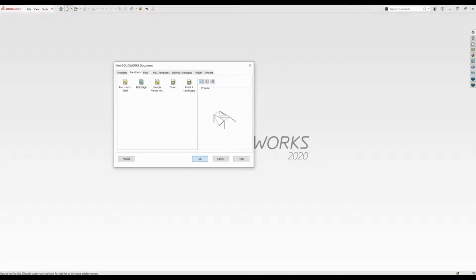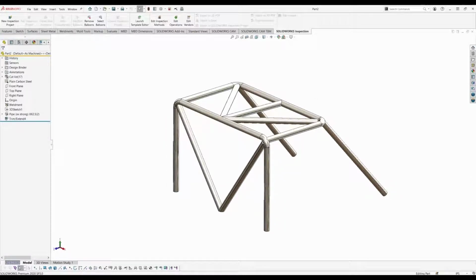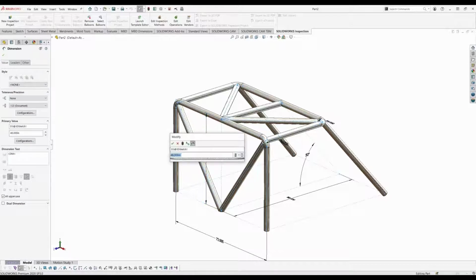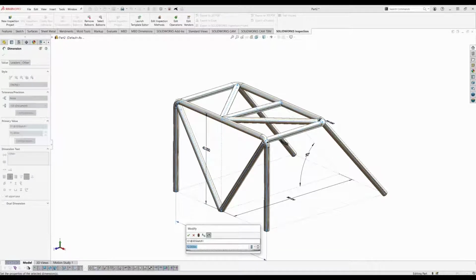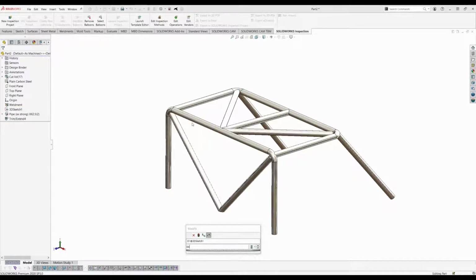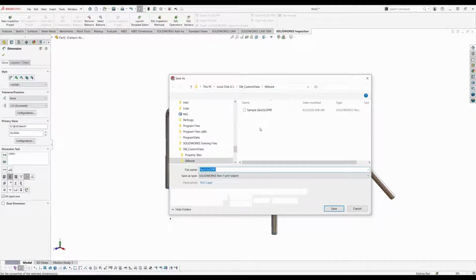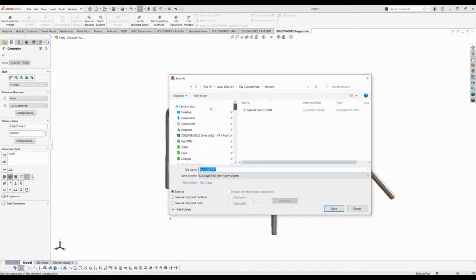So when we go and fire up a template, it's already got the weldment in it, it's already got all of the features in it, it's got extruded cuts and the swept features, and all of those exist. And in this case, I have one singular sketch that's driving the design. So if I wanted to make it a flatter design than what this roll cage is, we might make it 42 tall, and then it's going to have a wide stance, so we might make it 7 feet or something similar. And just those few changes, I now have a finished roll cage that's per our specifications, and we can save that into our project. So just by using a standard file save as inside of SOLIDWORKS, we'll go ahead and navigate to our vault. We'll go ahead and access it through our quick access area, and we'll go back into our project.